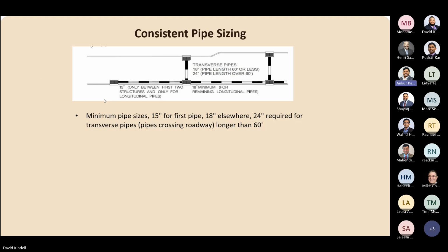And when you're drawing these pipes, make sure most MDOT roadway inlets can fit an 18-inch pipe, but just be careful with yard inlets and things like that. Depending on the detail, some have a maximum pipe size of 15 inches. So you have to take that into consideration when designing it.